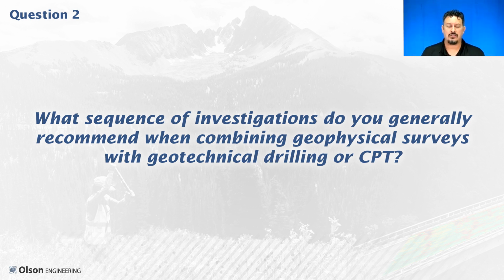What we were doing was we actually modified our CPT truck so that the first section of downhole rod had an electrode on it. And we were trying to leapfrog back and forth of doing a resistivity survey, and then from the interpretation of that first section, choosing where to start doing a CPT push.